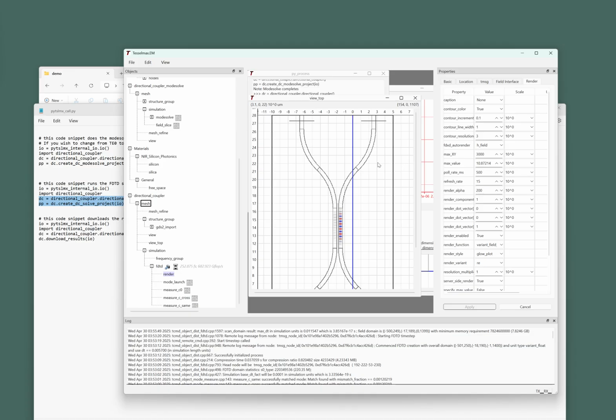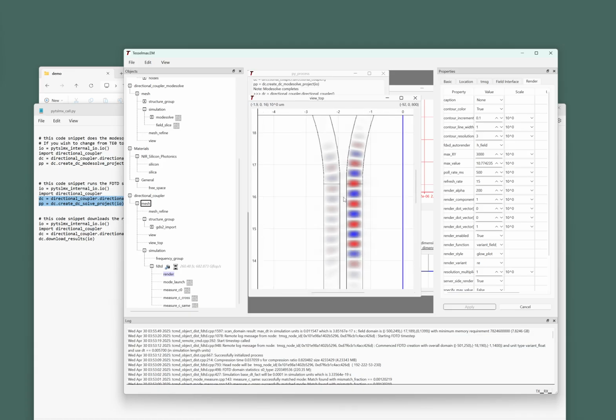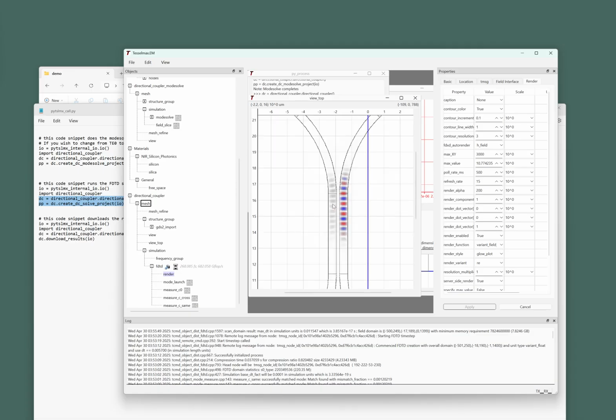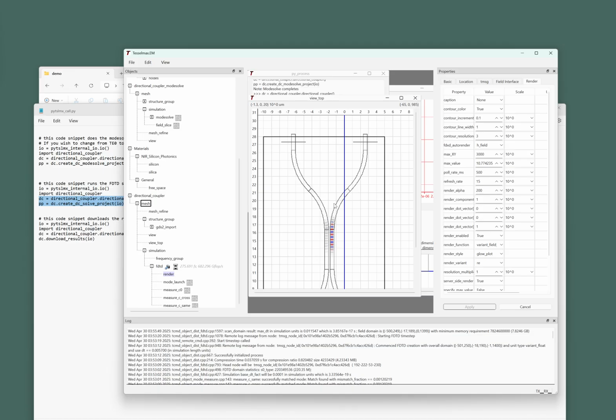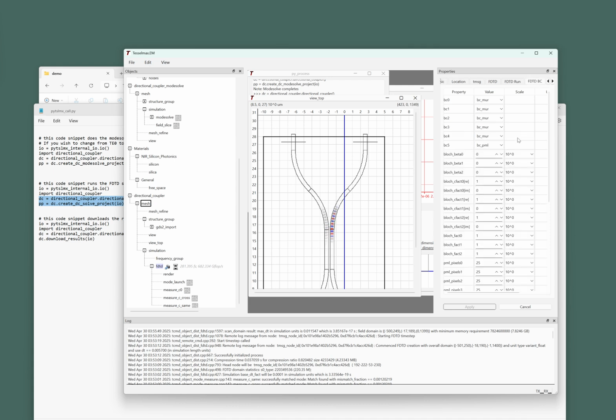So as far as the physics that are going on, you can see the standard directional coupling thing. And there's a 90-degree phase shift, it looks like, between the two modes, which is what you would expect. And what else can I say about this simulation? Yeah, I set PML boundary conditions to be the top end.